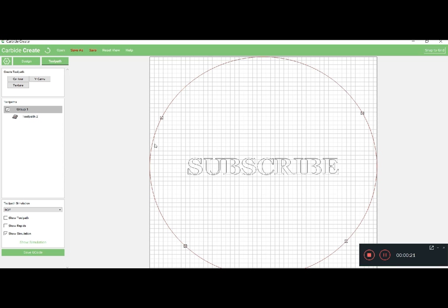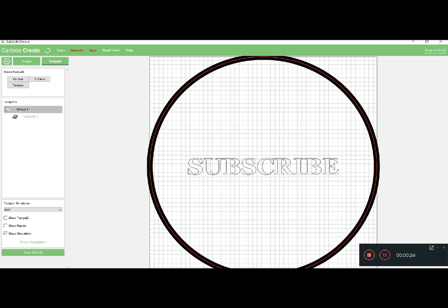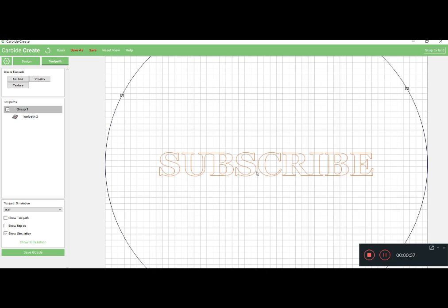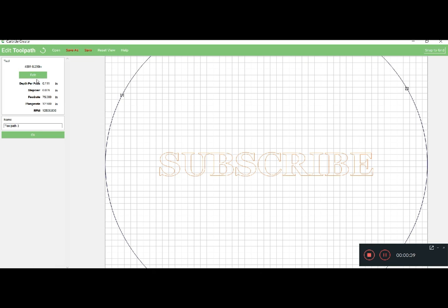And you don't really want to use the same bit. Let's just select the subscribe. If I were to hit contour, we already have that 201 in. It's not going to work. You're not going to get those nice crisp lines. So what we're going to do is V-carve. Now we can either use a 90 degree, we can use a 60 degree, you can use whatever you want, but you can see the 201, even though it will do it, it's not going to be very crisp.